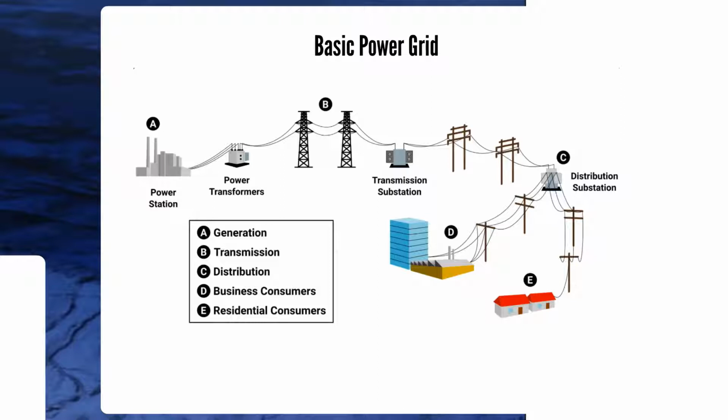As it relates to the transmission part, we're going to encounter losses. These will be due to the resistance of our conductors and also the heat that's generated when current flows through the conductor. As it relates to the size of the conductors, the larger the conductor, it will cost more, it will be difficult to handle, and it will generate less heat.